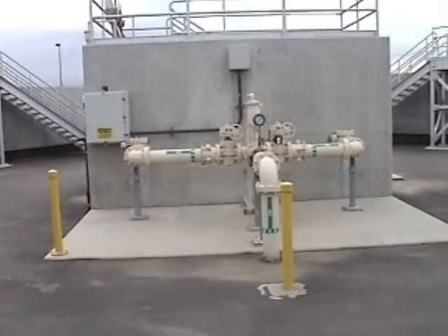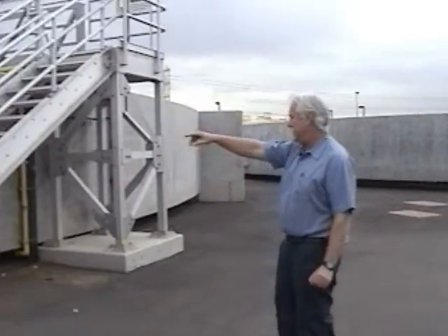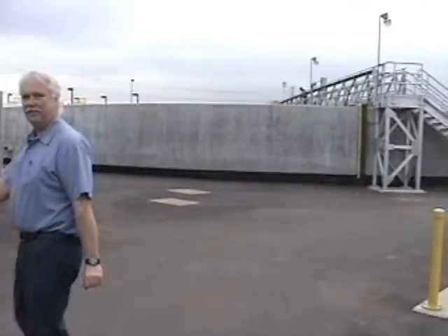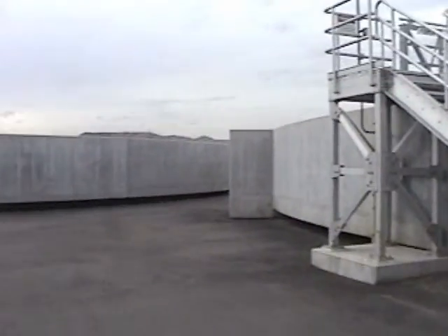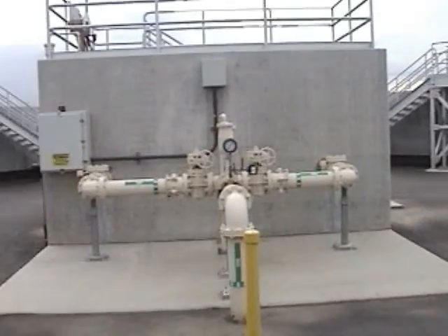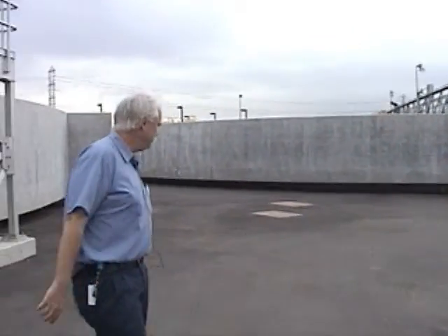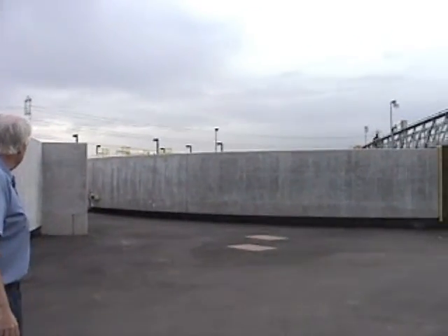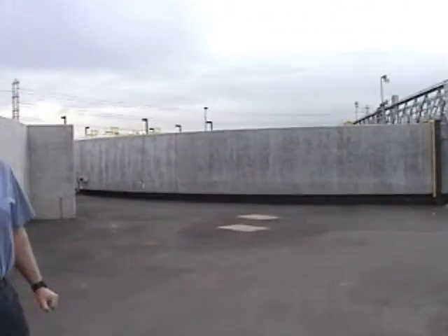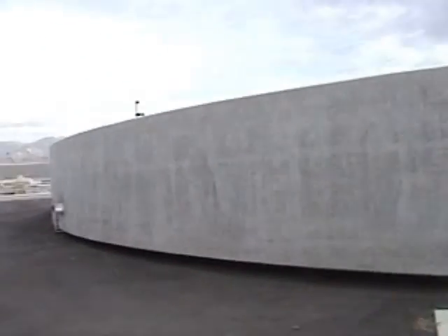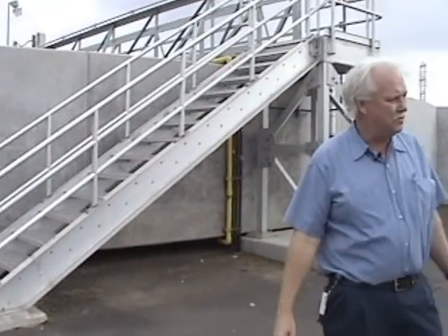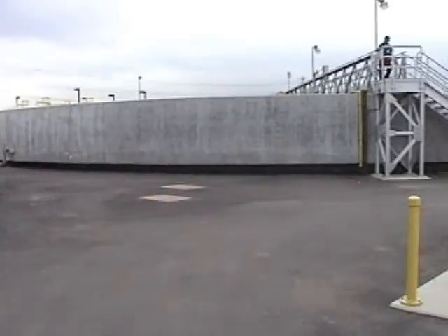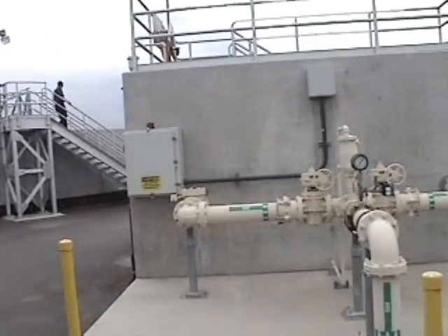Right now we're standing in the center of our 4 secondary clarifiers. That's 3A, 3B, 4A behind you, and 4B. Again, the numbering over here is a little unusual because the expansion will be clarifiers 1 and 2. So these are the secondary clarifiers. The flow is exiting the aeration basins through the RAS pump station, and then here we are at the secondary clarifiers. Right now we have 2 secondaries online. We're flowing about 10 MGD per day, so we've determined that that's adequate.